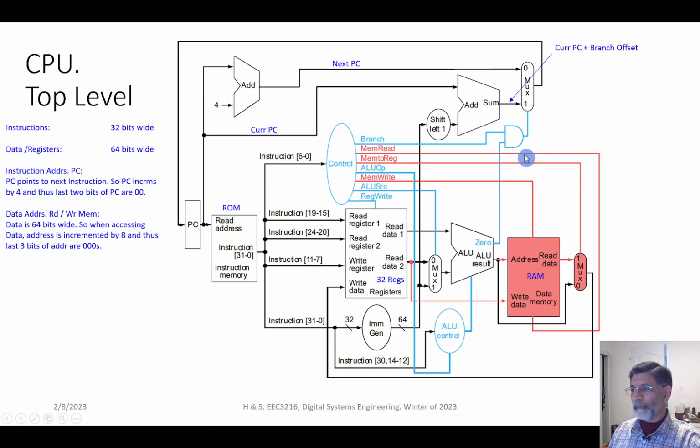So one of the first blocks we can narrow down is the PC section. And like I said, PC is used to point to the next instructions. This would typically be a read-only memory where the instructions are stored, and the PC will point to the next instruction to be read from this memory.